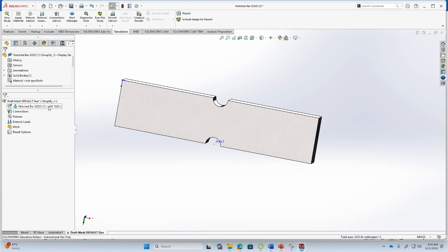In SolidWorks, the material application is on a part level. So if you have more than one part in the assembly, then you will have to separately apply the material to each one of them. Okay. Sometimes the same part can have different materials in different regions as well. Okay. So again, you can do partitions and other things, but best is to then keep them as separate parts and then create an assembly, right, and assign the different materials. So like I said, SolidWorks has some limitations in terms of the analysis capabilities, but they can be overcome quite simply if you know workarounds.